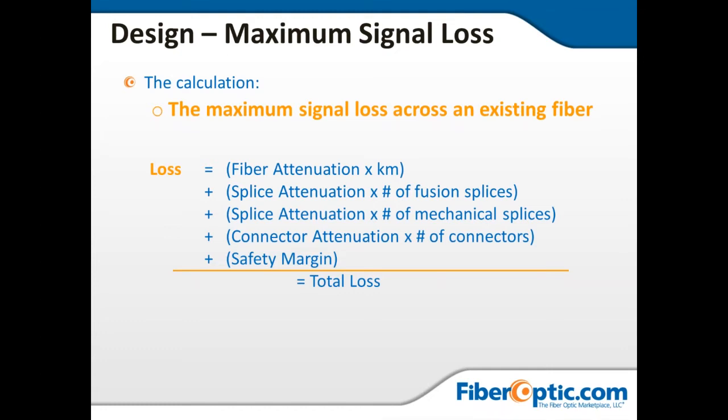But the budgets for outside plant average out of the EIA, or excuse me, the IEEE, would represent a budget of a 0.1 max. Even that in most environments is not acceptable for a fusion splice, since we should get fusion splices in the 0.01 to 0.03. Most of your clients or most of your designs are not going to be designed in the 0.1, but 0.1 would be a budget number, but you should get much less out of that.